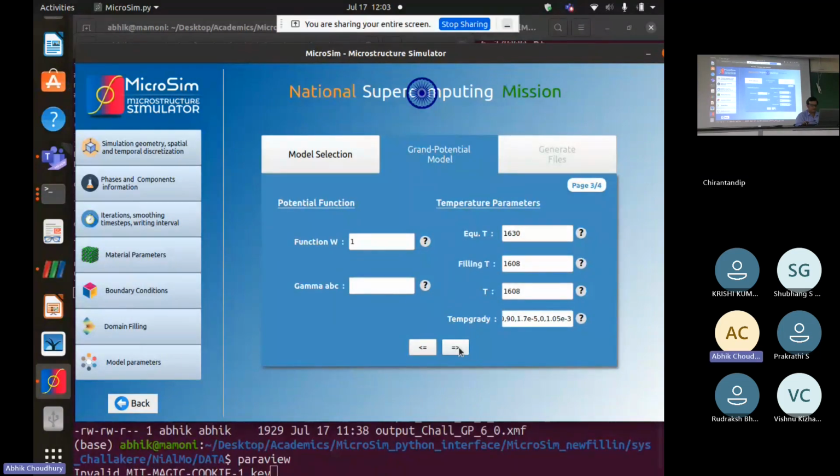And here we are using a temperature gradient in the simulation, as you will see here. So we are imposing directional solidification conditions, where you impose a temperature gradient across the solid-liquid interface and translate it with a given velocity. This is precisely what you have in a Bridgman setup.